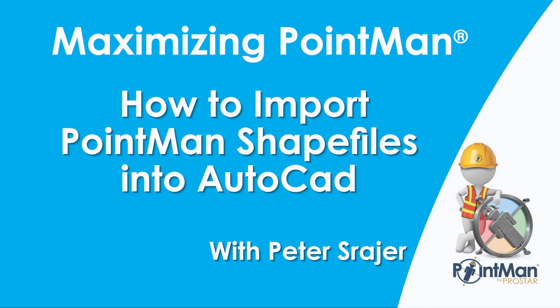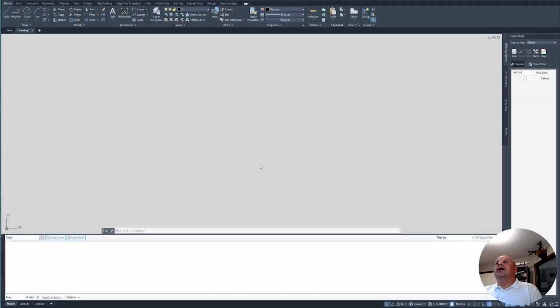I'm going to show you how to bring in PointMan exported shapefiles into an AutoCAD environment. First things first, I am using Autodesk AutoCAD Map 3D 2023 version. The same process will apply with Autodesk full version and within Civil 3D as well.